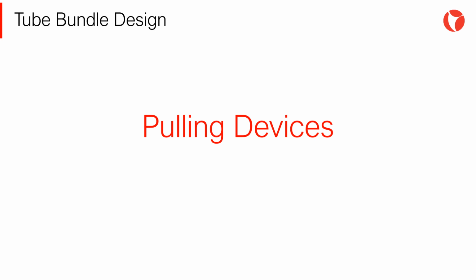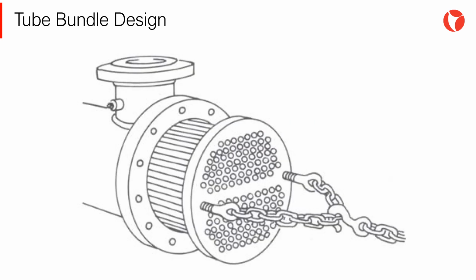For cleaning and maintenance operations of shell and tube heat exchangers with removable tube bundles, devices and accessories to facilitate the extraction of the bundle are needed. For removable bundles, the tube sheet must be designed including threaded holes for pulling devices. These holes must be covered during normal operation to avoid fluid sedimentation, possibly damaging the thread.